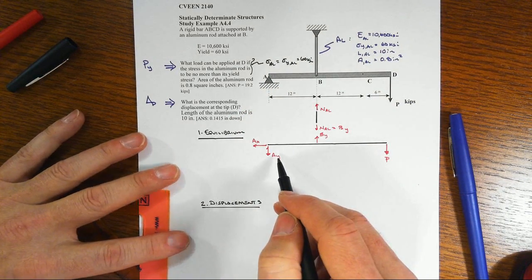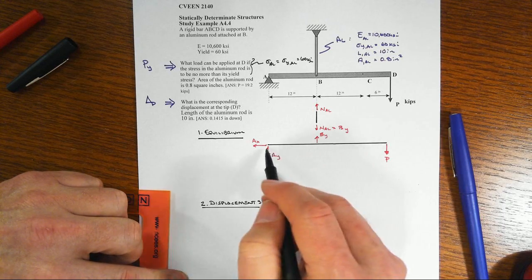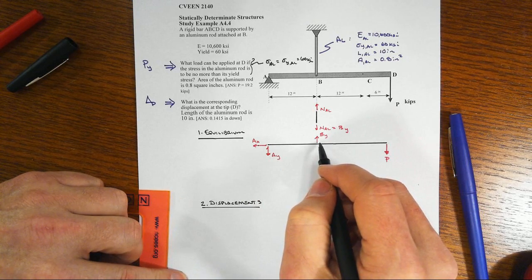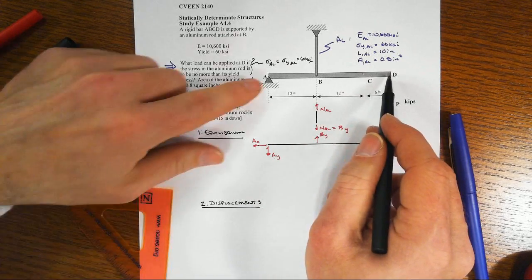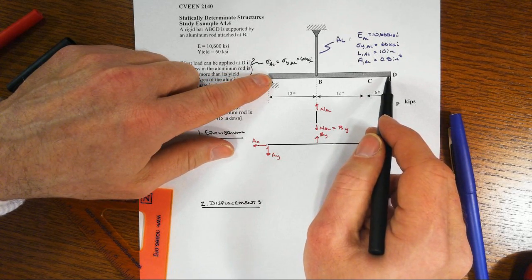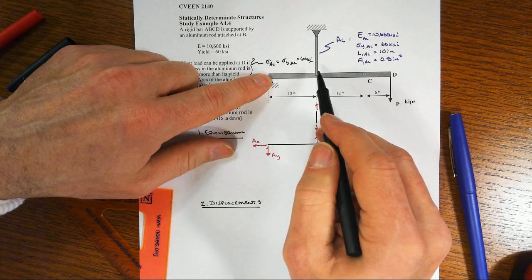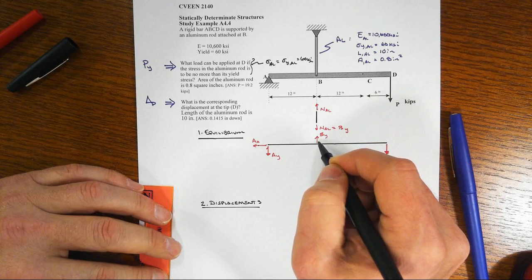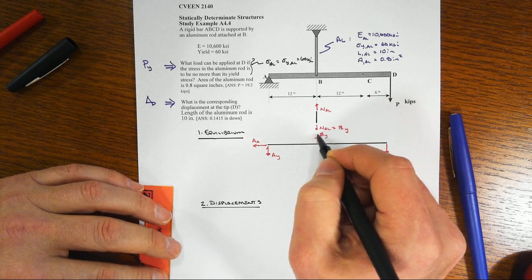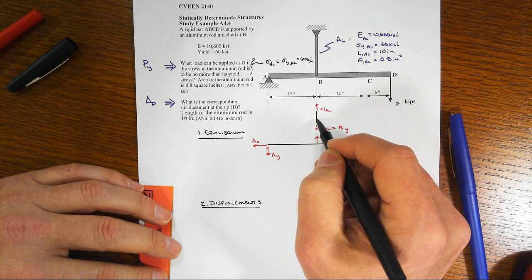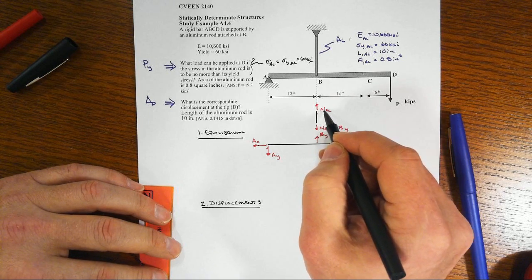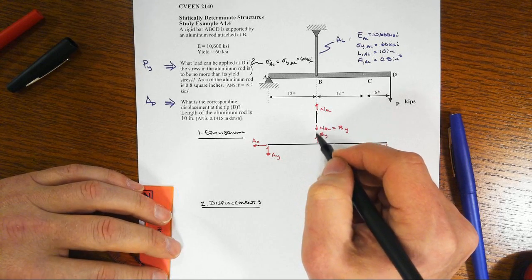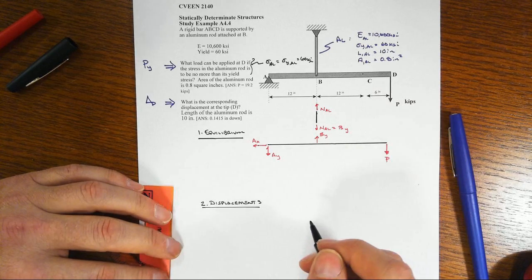So I already got started with the equilibrium. Here I've got the free body diagram of the beam. Notice that I've got the two reactions, AX and AY, the applied load P, and then it's relatively intuitive that if we're, in this case, trying to pull down the supports over here in this bar, it wants to rotate in a global clockwise fashion, which would want to extend this aluminum rod. That means it's going to put the rod into tension. Right, so we see this B sub y, and then I've chosen to also show the free body diagram of the aluminum bar. We've got an axial force, NAL, and notice that, hey, these two have got to be the same. They represent the same thing, and so NAL is equal to BY.